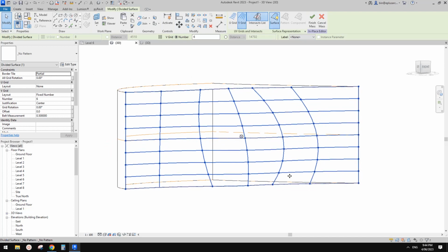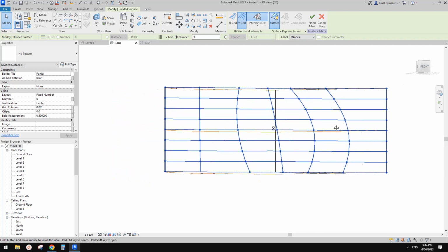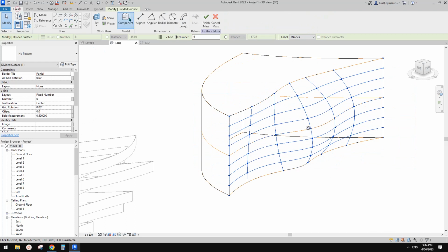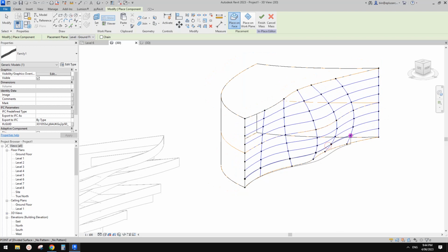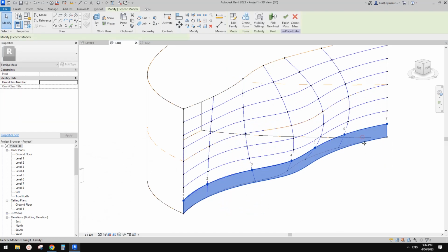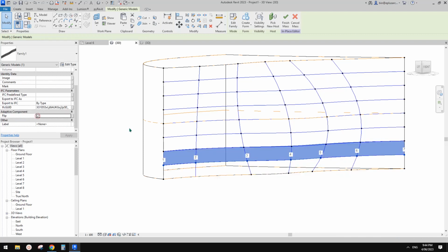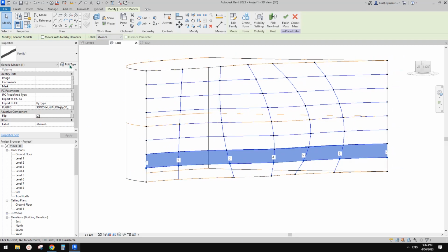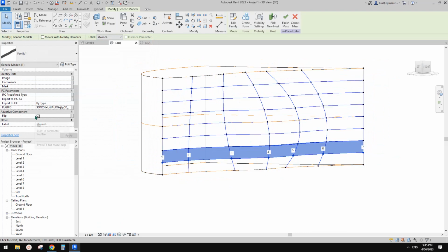Okay, so now we have all these grids. They are perfectly matching the levels. So now let's do it again. So create component 1, 2, 3, 4, 5, 6, 7. Okay, so still going the other direction, but that's fine. Oh, hang on, can we flip? Yes, we can. Great. So which means we don't need to go to edit tab and change the angle. But that's another option. So you can just type in 180, so it will go up. But you can also flip.